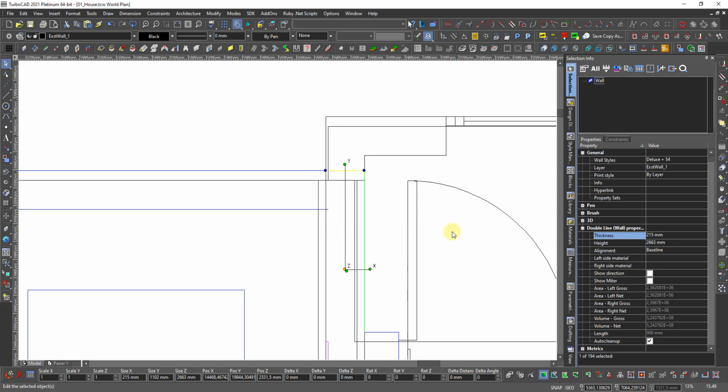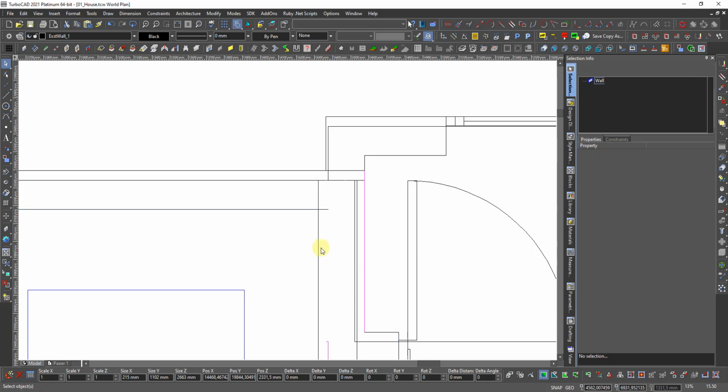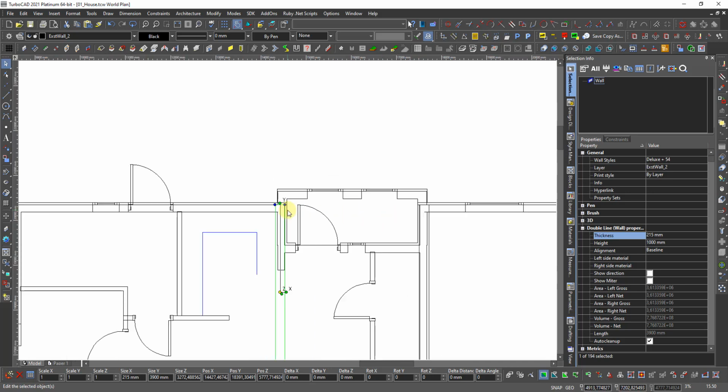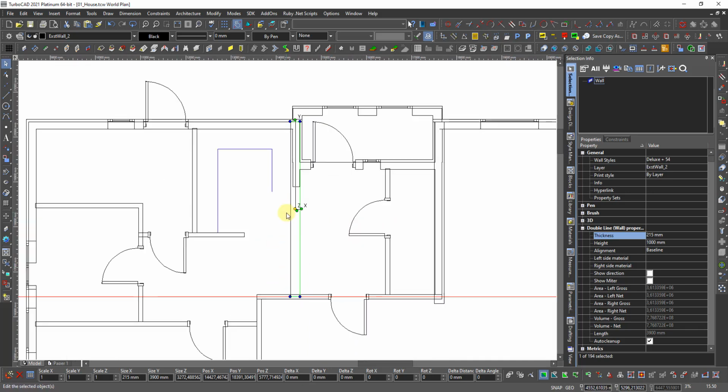This is stair wall 1, Deluxe wall. And this wall is stair wall 2, the tab. So this one should be moved in 54 millimeter because it should stand flush here and here. So then I move that in X 54.